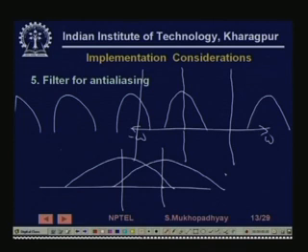So, what will happen is that effectively once these two lobes, if you take summation, then you are going to get a frequency spectrum of the digital signal that will look something like this. So, you see that, but this is a very important part of the signal. Generally for control, the low frequency part is very important. So, you see that the high frequency part of the signal, which was not so important for control, has kind of folded back and it has come onto the low frequency part and is now affecting the low frequency part, which is important.